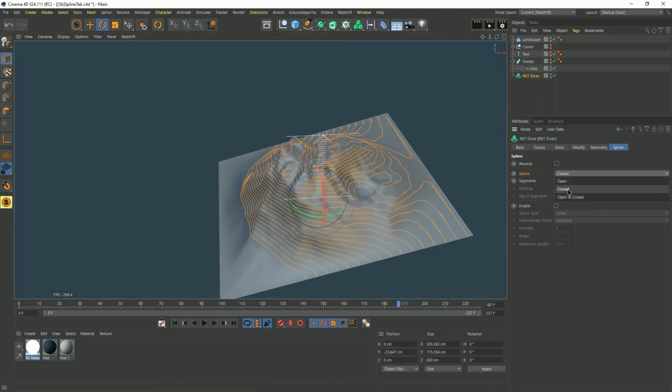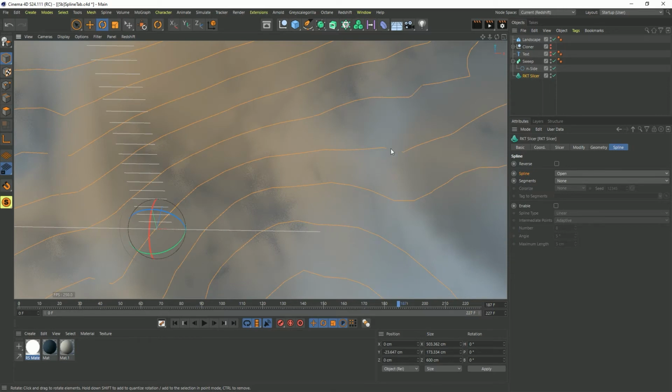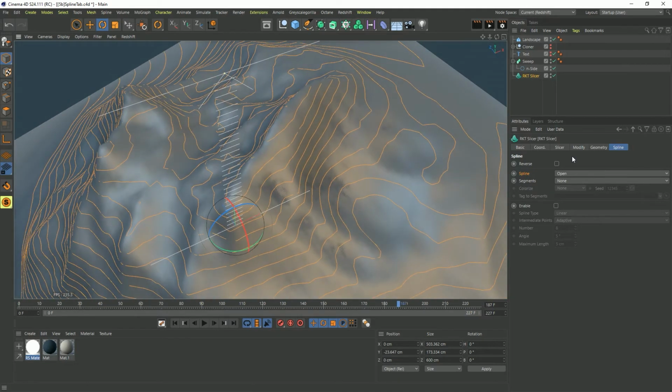How about we set that to be open instead? Well, if you set it to open, all these other splines are going to have an open edge somewhere that doesn't quite connect. So you can see if I say closed, all these little lines all over the place suddenly look a little bit different. Bing! You see like right there, that gap suddenly appears because it's now an open spline, doesn't close.